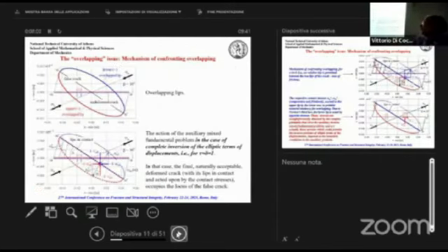You can see here the overlapping lips. You see the red one, which is the upper lip, becomes the lower lip, and the methodology adopted to overcome this solution. In fact, the linear terms of the displacement field rotate the crack as a rigid body in a position called false crack by Theoharis, and then the elliptical terms of the displacement field transfer the point along the lips to their new position, which finally leads to overlapping conditions.